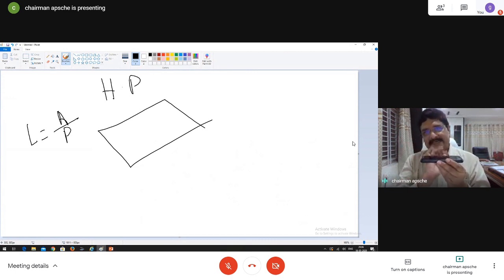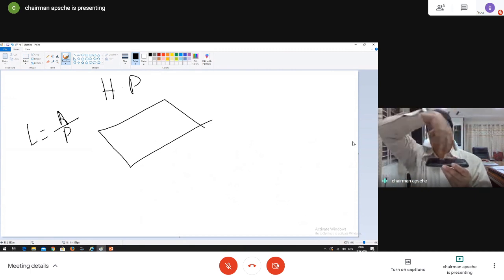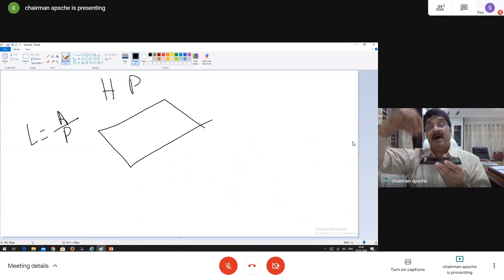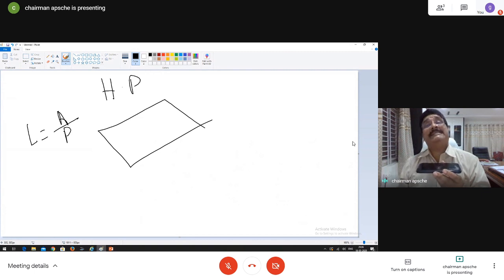Now it lost its heat, and it is now at the plate temperature. Everywhere here you have 80 degrees centigrade, lower density molecules. All of a sudden, it went to the plate, gave away its heat, and it is now at a reduced temperature. So, it becomes heavier, density increased.